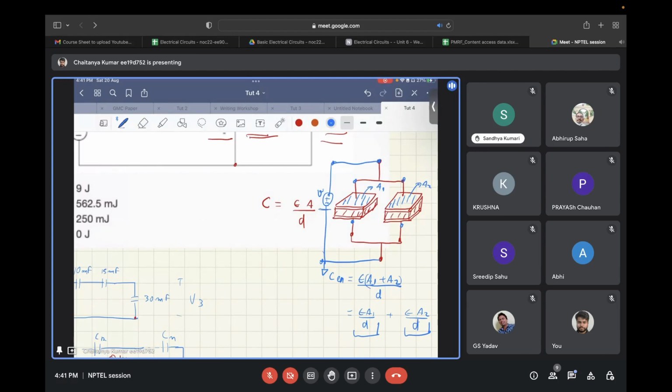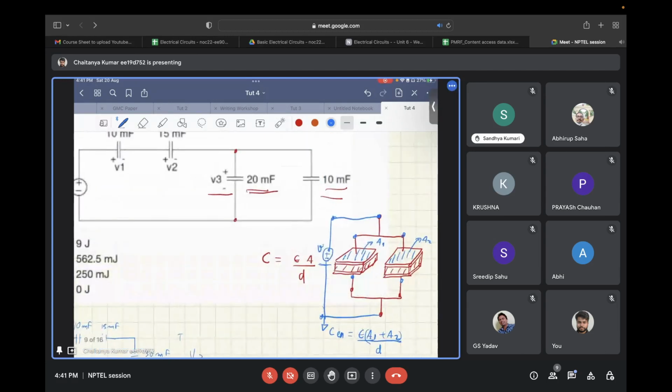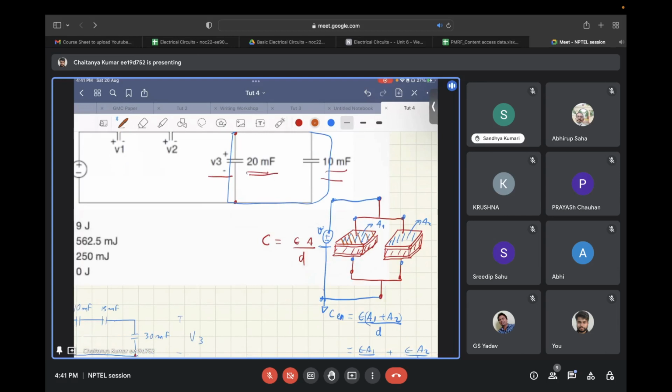So once you calculate the voltage of this combined effect, that will be the same that each of the capacitors will see. Now, what you can even further do is break this one capacitor into multiple slits, and you will have many small capacitors, and each of the capacitors will see the same voltage. However, since you need to find the energy stored on one particular capacitor,